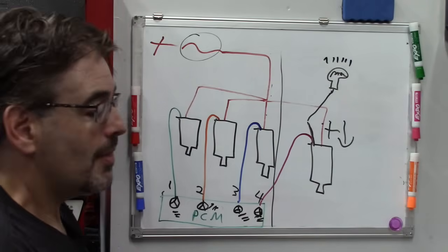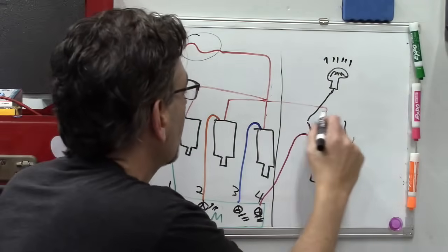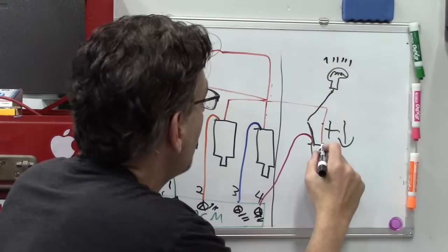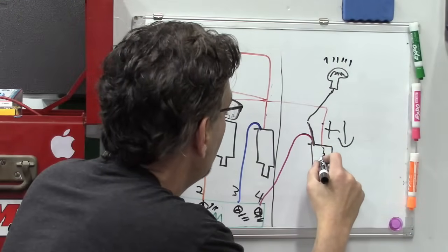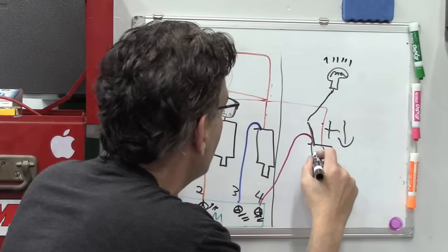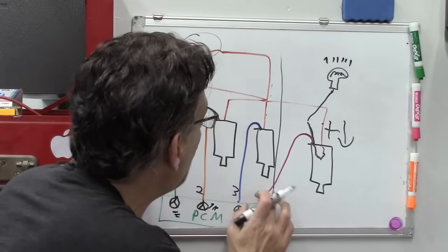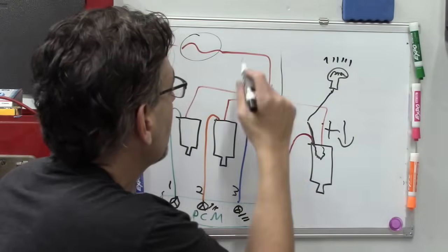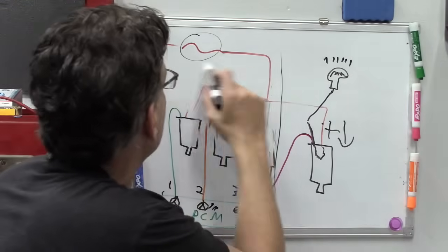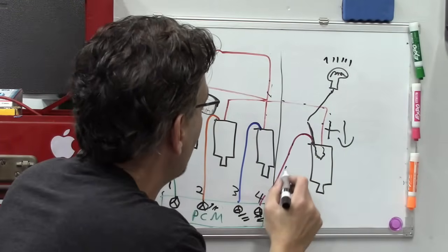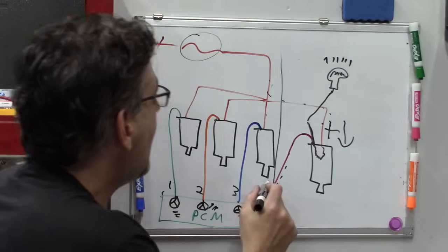Now, of course, that's because we've got the power coming through here. Remember the basic electrical training videos. The power is coming through here. It's going through the coil in the injector and then to the ground, but this is open here. So remember, filling the hose analogy from our basic electrical, we're filling the hose with our electrons. They've got nowhere to go.